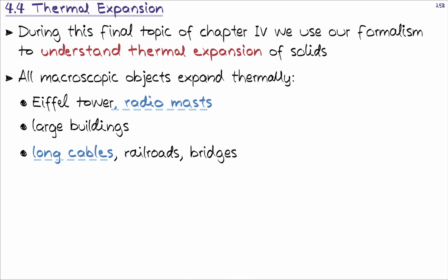With that, it's possible to change the dimensions of the wheel so that it can be slipped into its position. And when the system is restored to room temperature conditions, then the wheel will be securely tightened, and it can rotate.